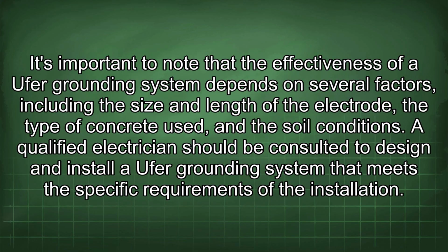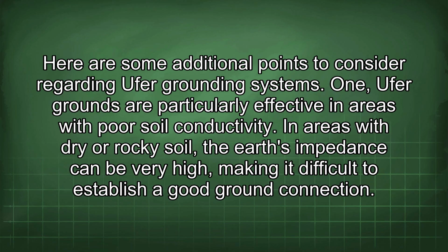This is essential for maintaining electrical safety and protecting equipment from damage. It's important to note that the effectiveness of a Ufer grounding system depends on several factors, including the size and length of the electrode, the type of concrete used, and the soil conditions. A qualified electrician should be consulted to design and install a Ufer grounding system that meets the specific requirements of the installation. Here are some additional points to consider regarding Ufer grounding systems.